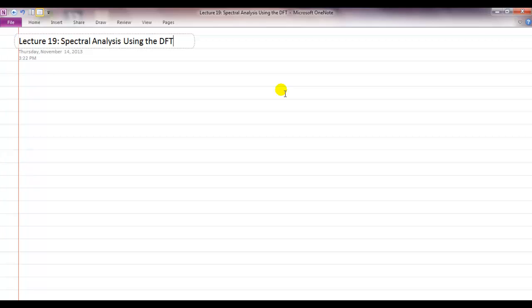But if you want to figure out how fast the plane is going, well, that's a spectral analysis question, because the fact that the plane is moving is going to give rise to the Doppler shift in your signal. So you receive your signal back, and you look at the new frequency of the signal; you know your original frequency, so you can figure out the gap between the two, you know the Doppler shift, and from that you can figure out what speed the plane was moving at.